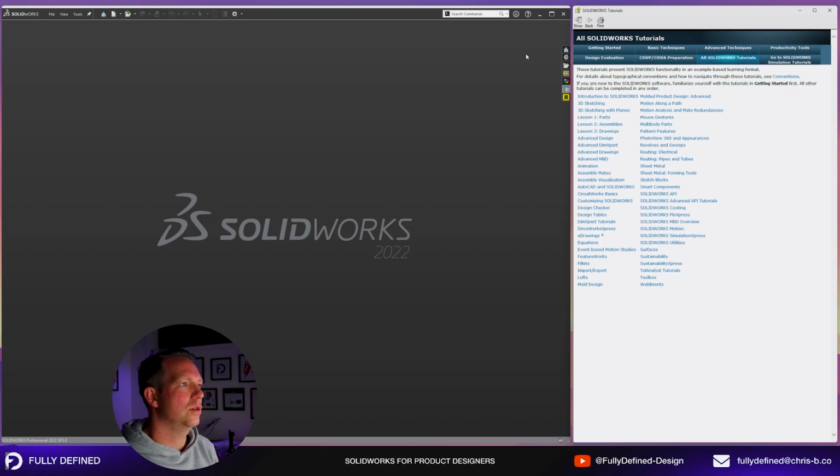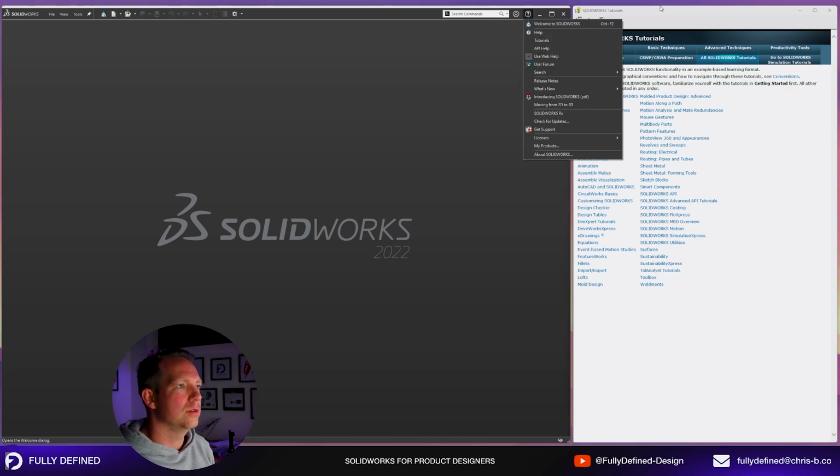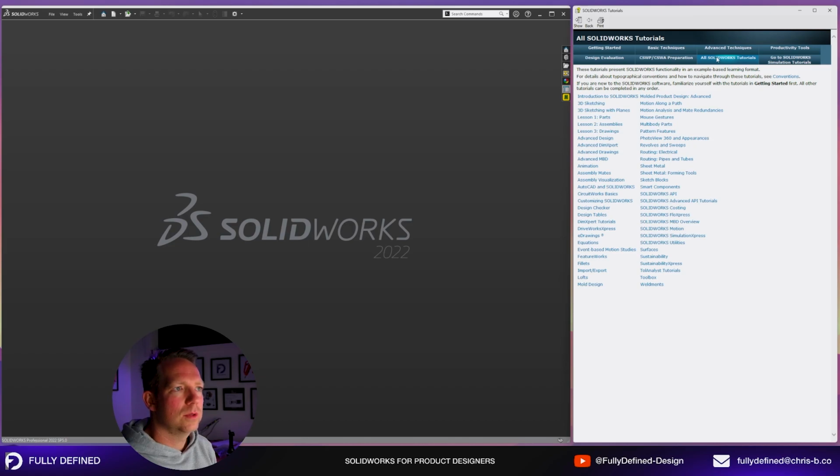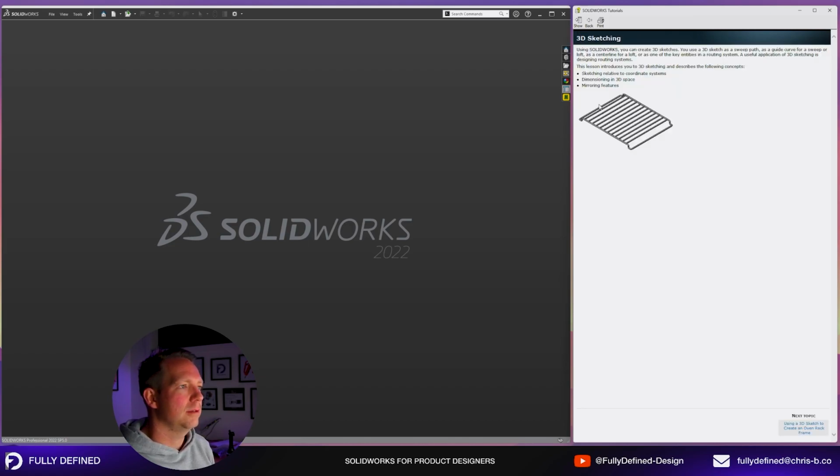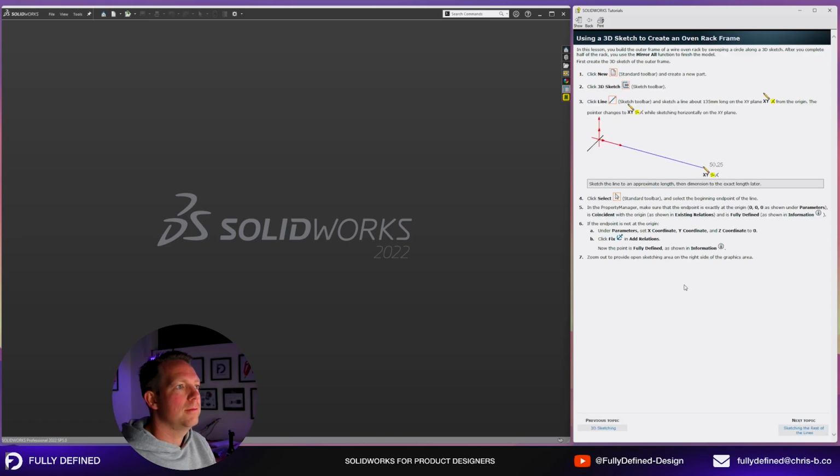So as always, to find the tutorials, click on the question mark, click on the tutorials. This window pops up. Click on all SolidWorks tutorials and then click on 3D sketching. Now, 3D sketching. Using SolidWorks, you can create 3D sketches. Use a 3D sketch as a sweep path, as a guide curve for a sweep or a loft, or as a center line for a loft, or as one of the key entities in a routing system. I've never done that. A useful application of 3D sketching is designing routing systems. This lesson introduces you to 3D sketching and describes the following concepts: sketching relative to coordinate systems, dimensioning in 3D space, and mirroring features. Let's get into it.